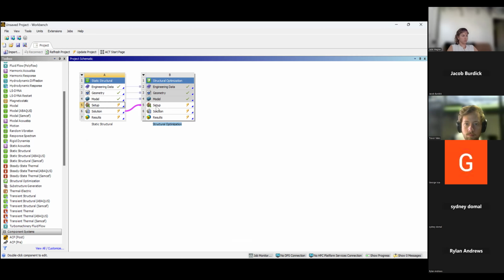Then you have to reset this study as well so that you can get whatever you want out of it. This is pretty much going to take your results and, based off of either mass recommendations or structural recommendations, take off material as much as possible until it meets those recommendations. Not mesh recommendations, structural recommendations, my bad. That's pretty much what it's going to be doing.